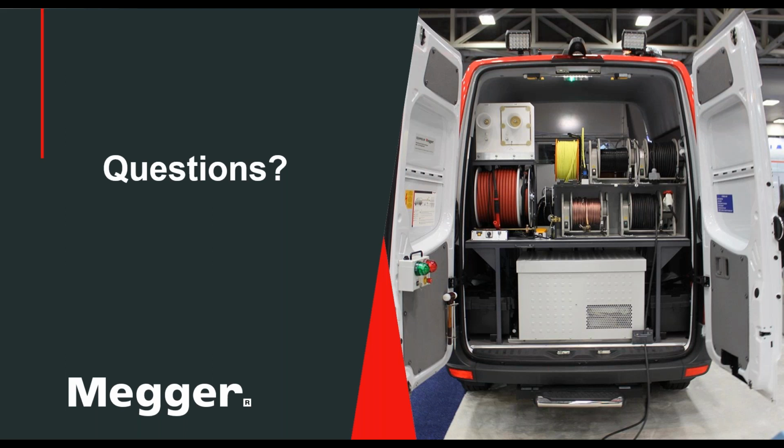Maybe one comment on this, because it's not totally clear from the question. If it says tripolar cable, so it's probably a segmented cable, has 3 segments, 3 phases in it. The question is, is it a belted cable or not a belted cable? If it's a belted cable, where you have only one common neutral for all 3 phases, you might also want to make sure you're testing phase to phase and not only phase to lead sheath, because if you have a phase to phase fault, you wouldn't find it.